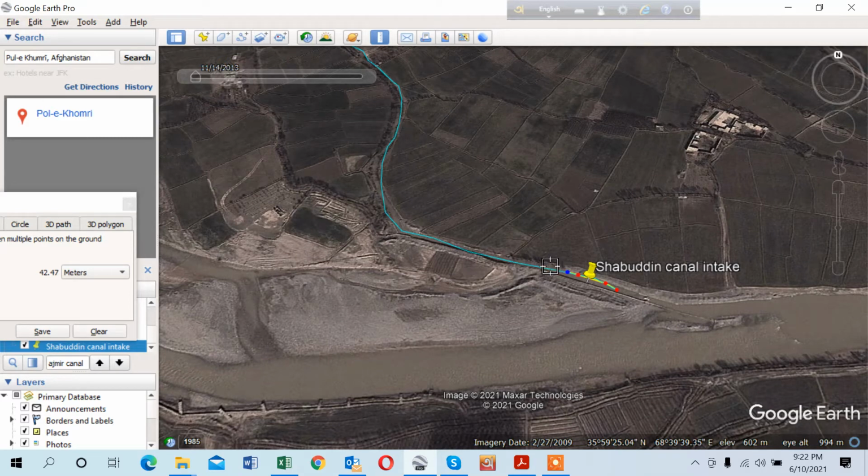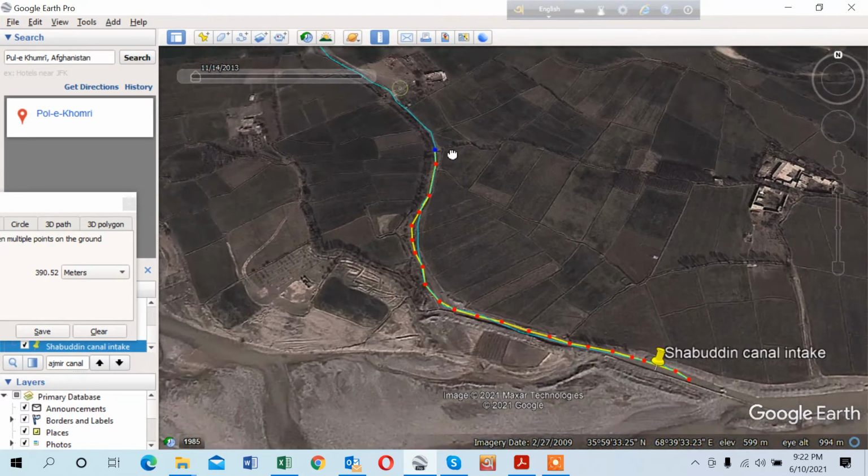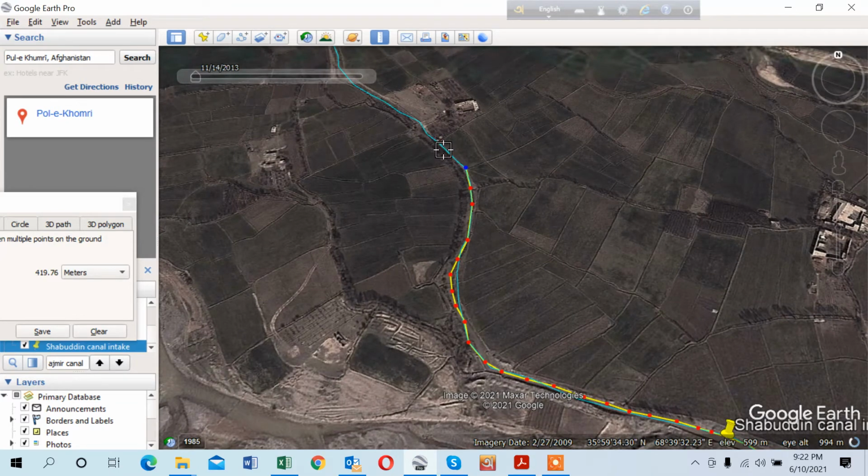In the irrigation planning, first you have to assess how you will run the main irrigation canal. If it is the existing canal, then you have to see how the existing canal is moving, and accordingly you have to make some planning so that you can get the sufficient grading.